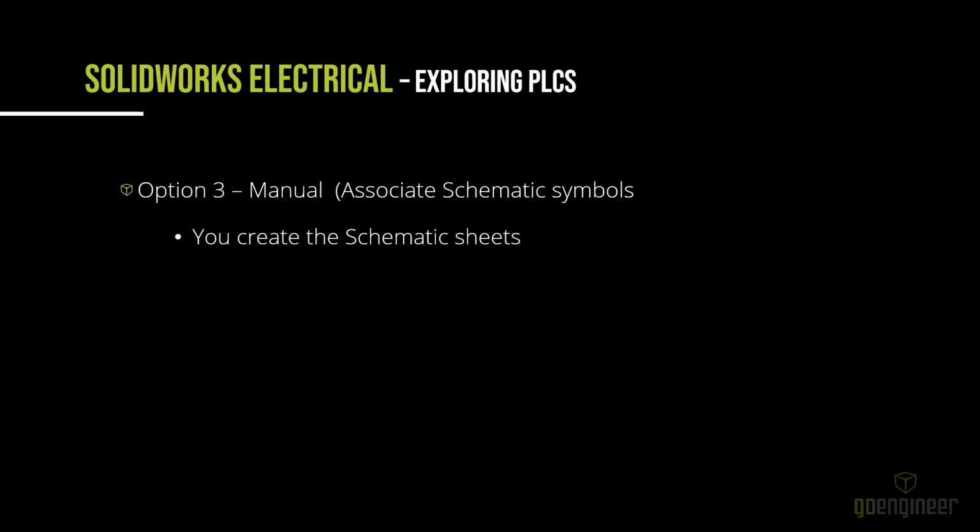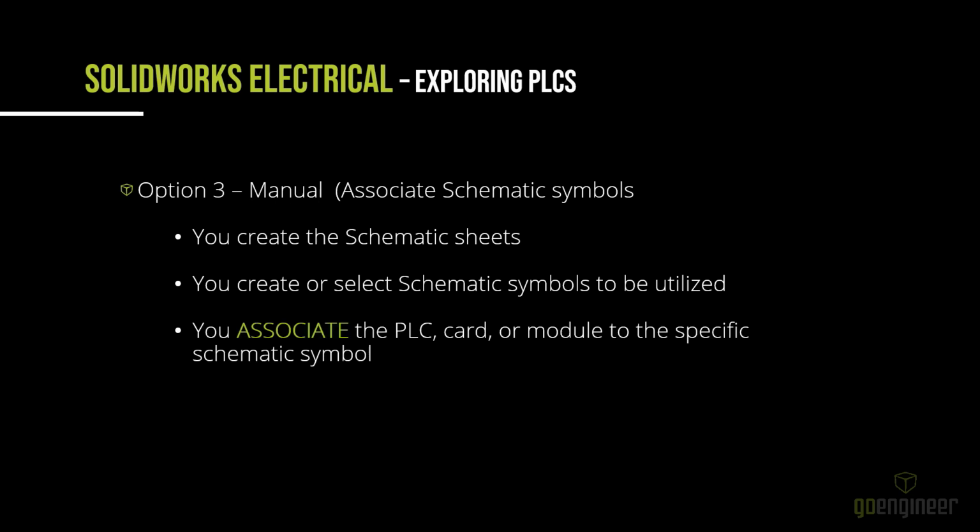Now, in manual here, where we are dealing with this, you are dealing with just associating schematic symbols. You are going to create the schematic sheet. You then create and select the symbols to be utilized. You then associate the PLC, the card, the module to that specific schematic symbol.